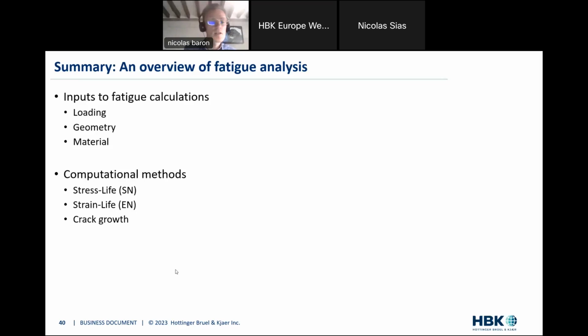That's key, and I'm insisting on that here because it's often overlooked by newcomers in the world of fatigue calculation. They just assume some generic loading. They do the design the best they can, and that's fine. But having missed the right loading in the first place will result in their design not being robust against real life conditions. So I'm maybe a bit repetitive here, but it's really vital to take into account the right loading when designing your items, your components. So that were the inputs to fatigue calculation.